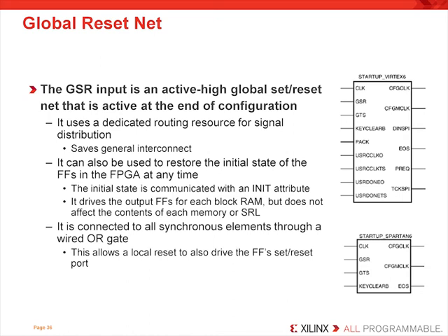The output register of the shift register LUT, block RAMs, and the DSP slices can be initialized when the GSR is asserted in just the same way. But the memory contents of the shift register LUT and the memory contents of the block RAM resources will not be manipulated by the GSR. So as long as the device is not reconfigured, the contents of the shift register LUT and block RAMs will remain. You should also note that effectively the GSR-net and the local resets are ORed together on each flip-flop's reset input. This means that the flip-flop can get reset either with a global reset or a local reset, which is of course what designers expect.